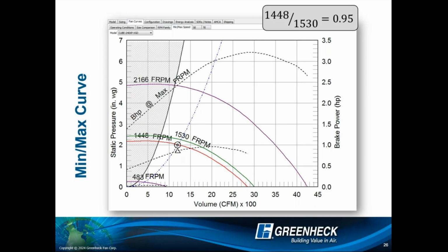All right. So in this scenario, I can look at this curve again and say, well, they show me my max construction limit. There must be motors I can upsize to that will give me access to that larger range. And that's exactly what we're doing here. If 1530 represented the 1 horsepower, maybe 1750 represents a 2 horsepower and 2166 represents a 3 horsepower motor.